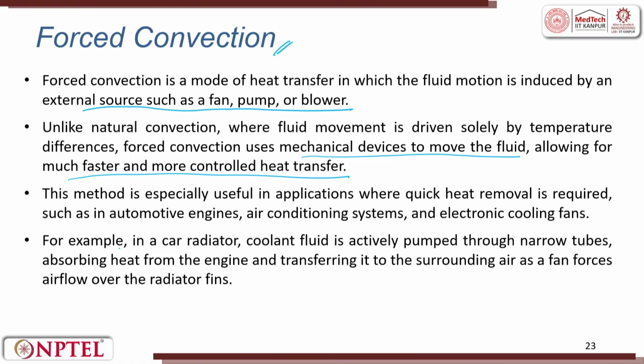For example, in a car radiator, cooling fluid is actively pumped through narrow tubes absorbing heat from the engine and transferring it to the surroundings as a fan forces air over the radiator fins. So, in order to extract heat, that is why in a radiator or in an AC unit you will always see a lot of fins. These fins are used for a larger surface for heat transfer.